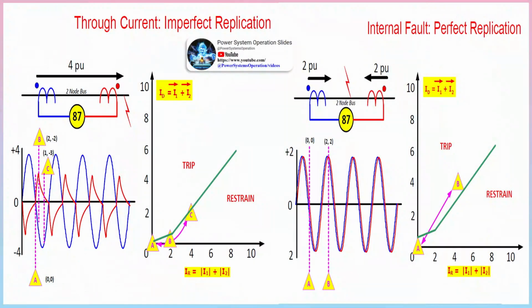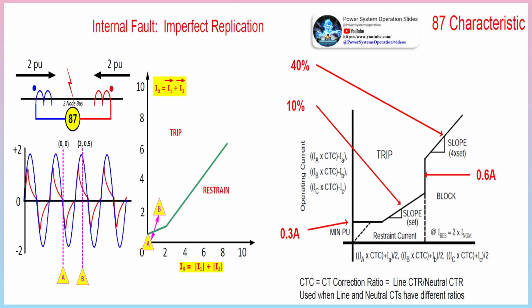Advantages: the scheme is secure against the effects of DC transients in the field rotor circuit. DC systems are prone to false alarms and false trips, so they sometimes are ignored or rendered inoperative, placing the generator at risk. The AC system offers greater security, so this important protection is not ignored or rendered inoperative. The scheme can detect a rise in impedance, which is characteristic of grounding brush liftoff. In brushless systems, the measurement brush may be periodically connected for short time intervals. The brush liftoff function must be blocked during the time interval the measurement brush is disconnected.